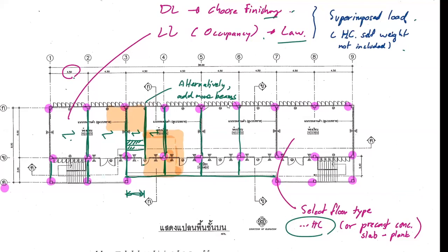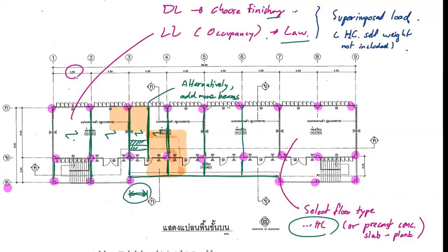as a simple beam. The hollow core is also a simple beam put on the steel beam, which is a simple beam as well. So when this span length of the hollow core is long like this, 4.5 meters, the bending moment acting on the hollow core is WL squared over 8. Am I correct? Yes. Now your L is 4.5.